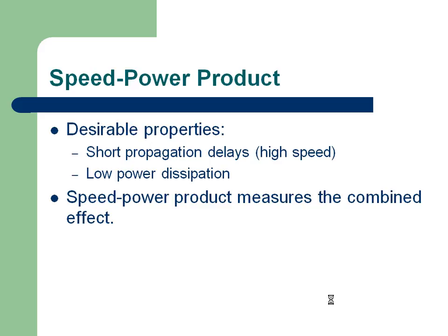So when you take the product, this level becomes again comparable to TTL and all. So in general, when you want to compare 2-3 logic families and comment which one is good, it is not appropriate to take only delay or only power. So take a product of them and define it. Among multiple logic families, whichever has the minimum value of this parameter can be considered a good logic family for that application.